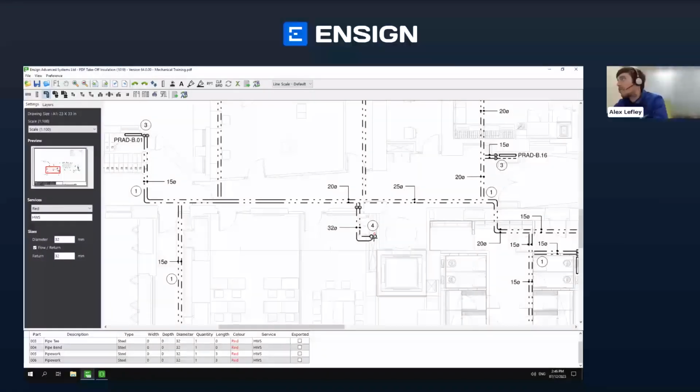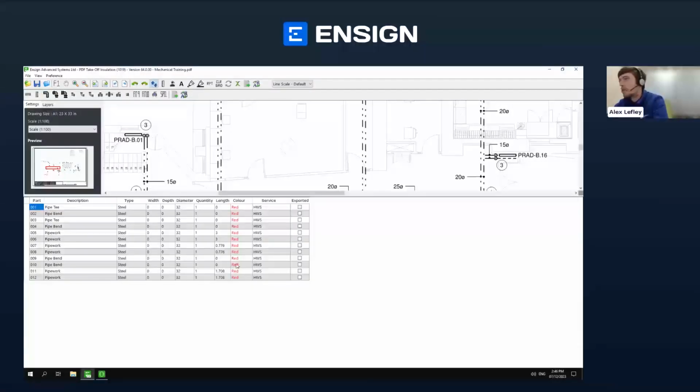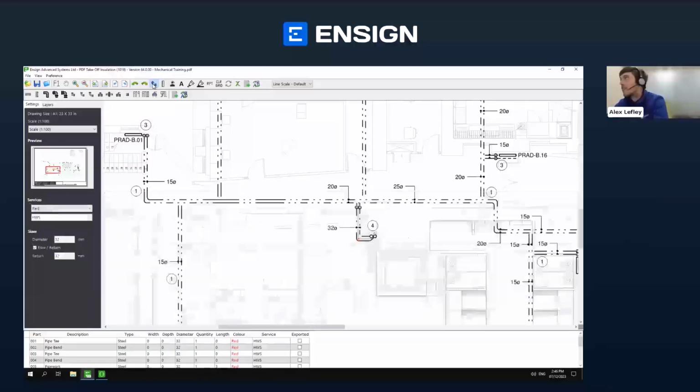And then I'm going to left click where I'm starting from, left click into the bend, and then left click up to that sort of T-junction there. And now that I've finished with that 32 mil run, I'm going to use my right click to say I'm done, okay? So the right click says I'm finished. And if I use these blue arrows that expand my grid, we can see all of my takeoff lines that I've just done there. So I'm going to send the grid back down.